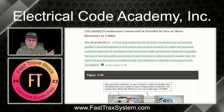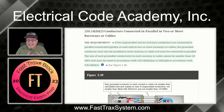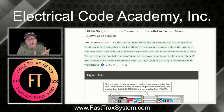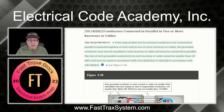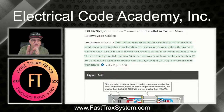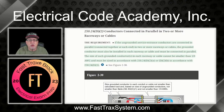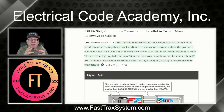You still have to do your load calculation. You still have to understand 220.61. You have to calculate what the maximum net value for the unbalanced load is. That's the value after you've applied any reductions. And you size your grounded conductors, and in many cases a neutral, based on that calculation. What we're saying here is that it can't be smaller than the instructions that are given here in 250.24(D)(2) when you're running a parallel set. And ultimately it's going to send you to 250.102(C)(1), the table. Okay, that's a lot to take in, but that's what we're focusing on.